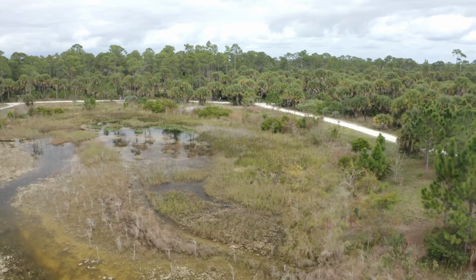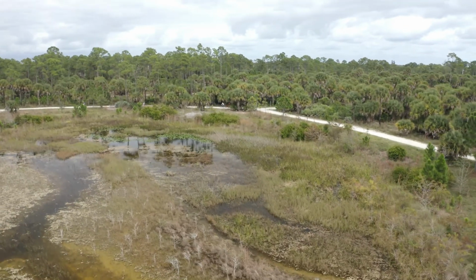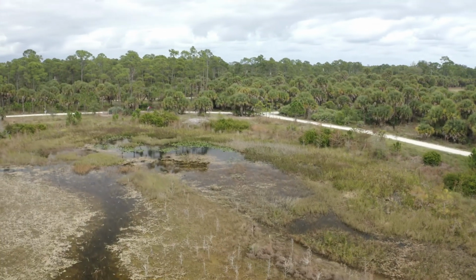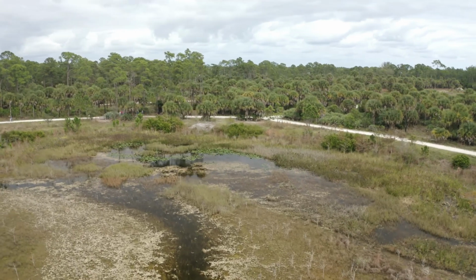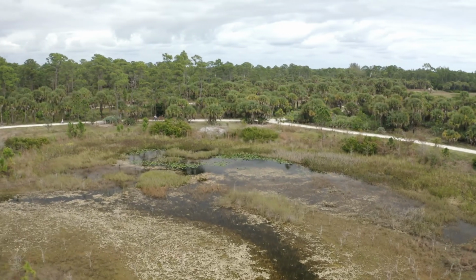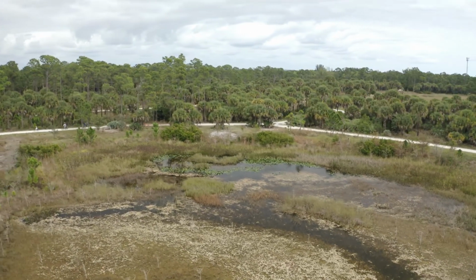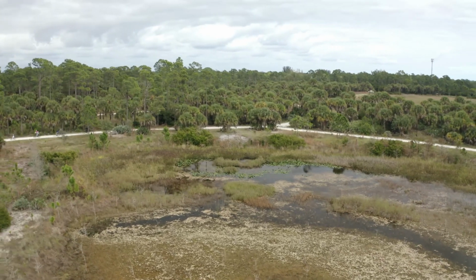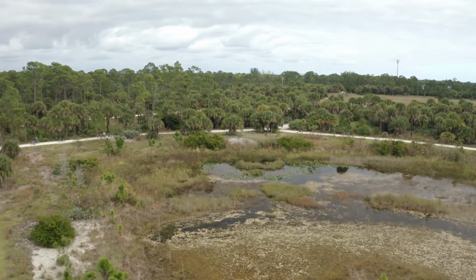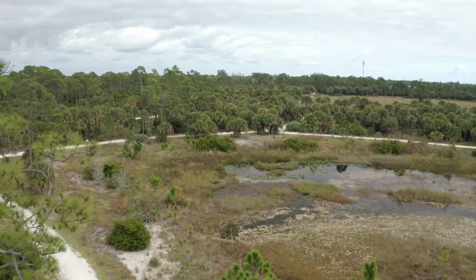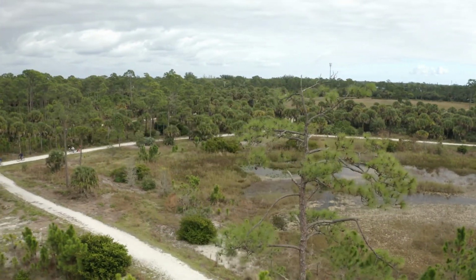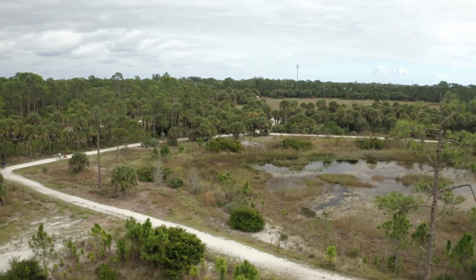With active track, there is no way I could have gotten those shots, because it's the drone that would have been deciding the flight path, altitude, and camera angle. So by using waypoints, you can really get creative by deciding the height that the drone should be above the subject, the distance of the subject, the speed, and the direction in which you want to point the camera. So let's create a test flight using waypoints.